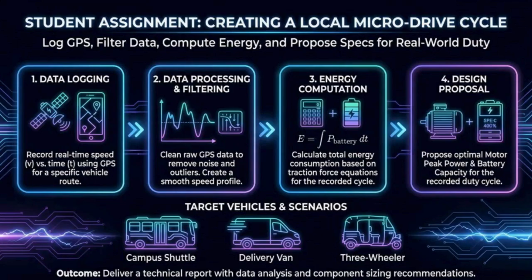From acceleration, compute total force. From total force, compute power. Then integrate power over time to find energy in watt-hours. Finally, propose the motor peak power in kilowatts and the battery capacity in kilowatt-hours. Design your EV based on your own real-world duty cycle.